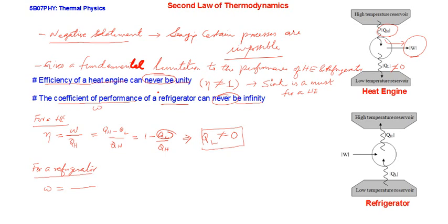In order to remember that one, if you don't remember, it doesn't matter. You recall the schematic diagram, which I have again reproduced on the right side. This is the second diagram, right? What happens here? Using work done on the system, here work was done by the system in the heat engine. So heat QL is absorbed from a low temperature reservoir and it is rejected to a high temperature reservoir, adding the work done, right? Our purpose is to cool down, means you have to further reduce the temperature of an already low temperature reservoir. So this is your desired outcome. I need not say the word output, a better word is outcome. So my desired outcome is QL.